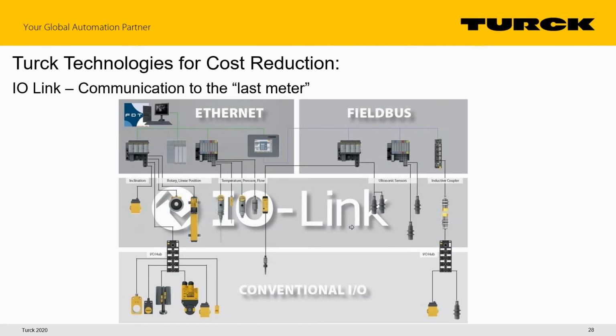If I have an IO-Link pressure transmitter fail, I replace it with a new IO-Link transmitter of the same product family, and it's just going to work because the PLC is going to have the ability to configure that device once it's plugged in, and there is oftentimes no spanning of the instrument. Most IO-Link devices are giving you full resolution across the full span, so there is no spanning of it. You plug it in, you're getting that full span data.